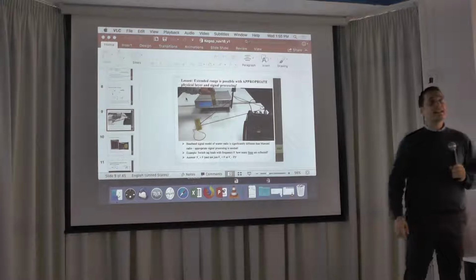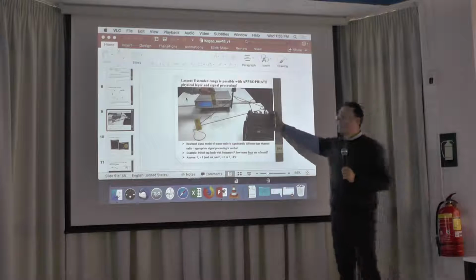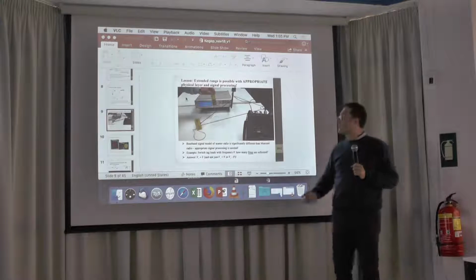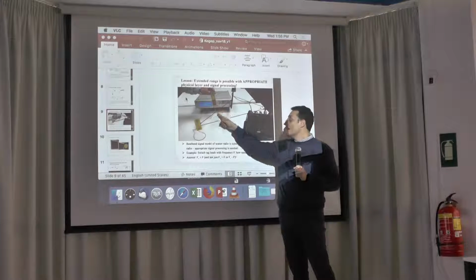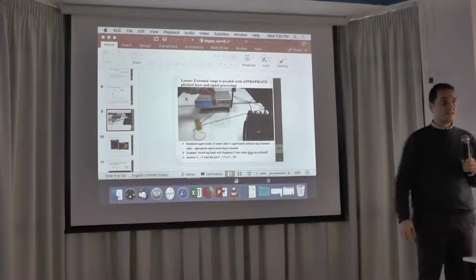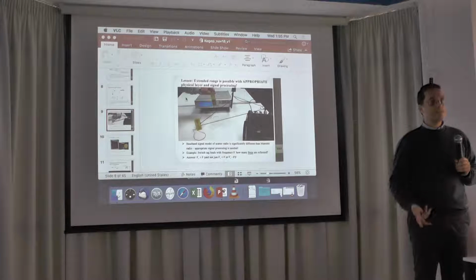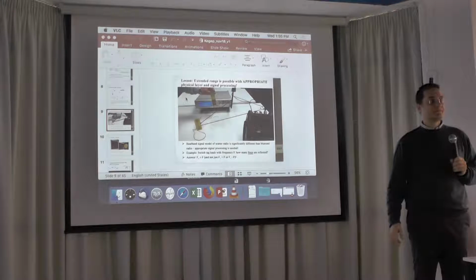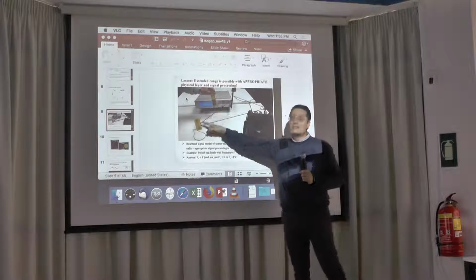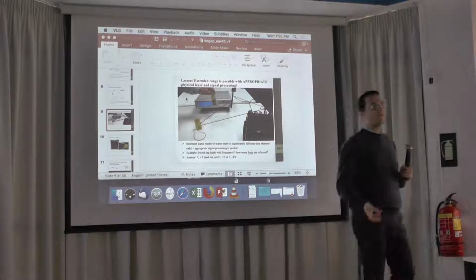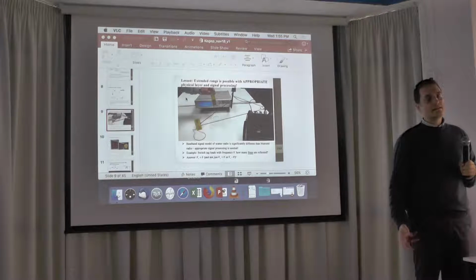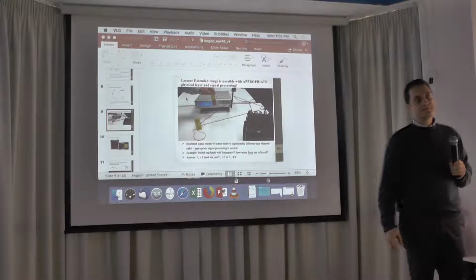measure. So essentially what is happening here, I can pick up the backscattered signal, and from that change of frequencies, I can find out what was the capacitance here, essentially what was the soil moisture inside the glass. So in a very simple way, I can measure soil moisture. Okay? And with a device that consumes very few microwatts of power. So I can build essentially very cheap sensors. Okay?